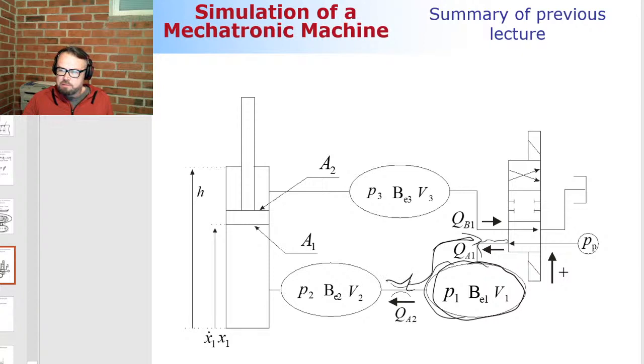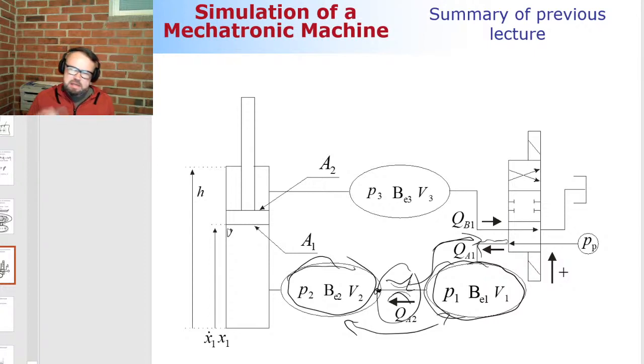Then we have here a throttle valve. In a throttle, there are pressure losses, meaning that we cannot assume the pressure here to be the same as the pressure here. That's simply because of this component. And now the pressure here can be assumed to be the same right after the throttle valve and in this corner of the cylinder. Maybe that's not exactly according to reality, but it's close enough as an approximation. And then on the way back, we just have one area, one volume where the pressure is computed. So that's how it goes.